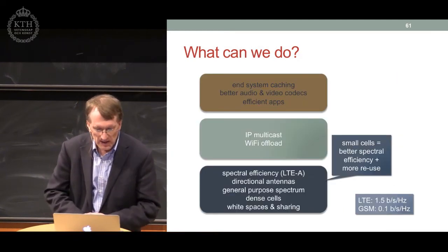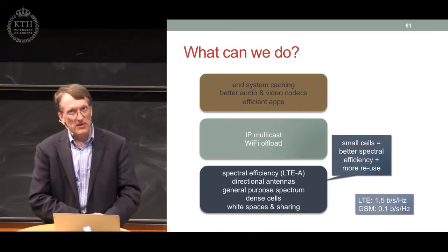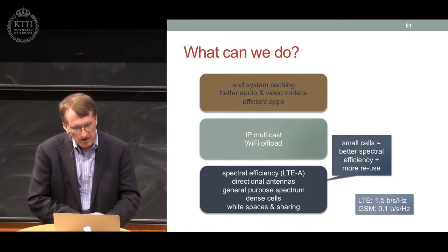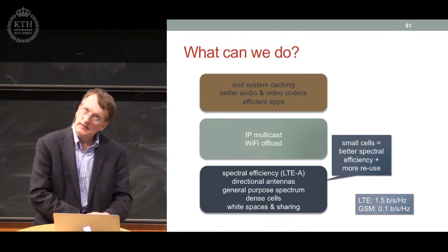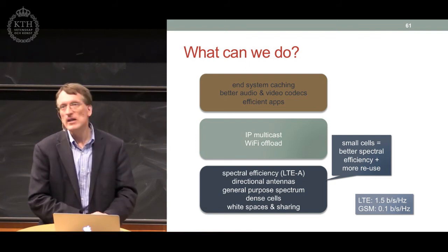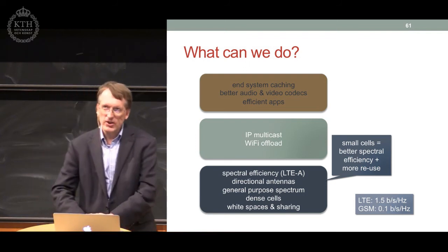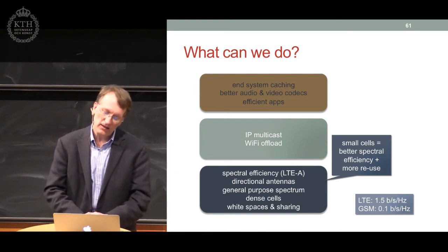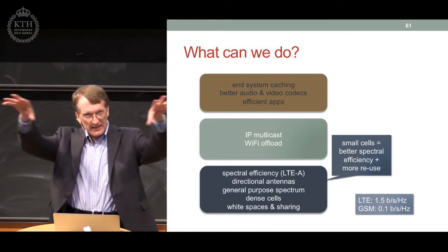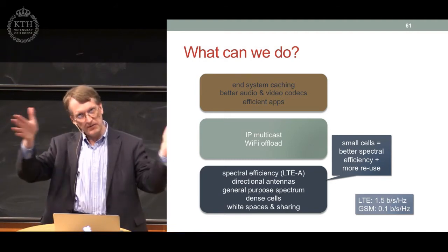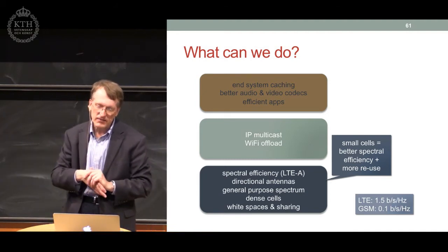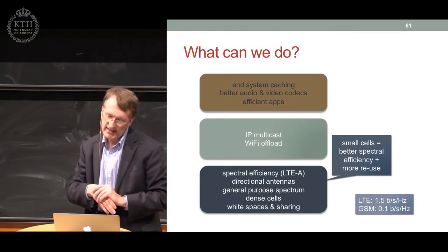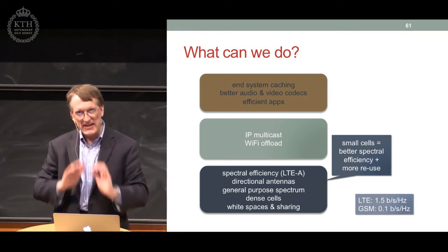So in total, what can we do? We can use much more efficient system design. We can use more spectrally efficient transmission mechanisms. Increasingly, we'll also see directional antennas. That's probably the most significant advance that's still available: instead of transmitting the same information to everybody within, let's say, a 120-degree radius of a cell tower, the typical cell site design, you'll now have narrow beams.